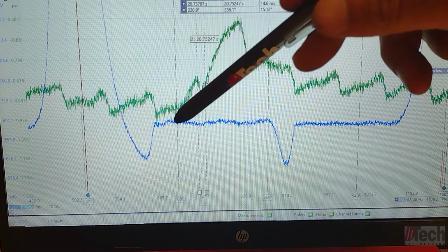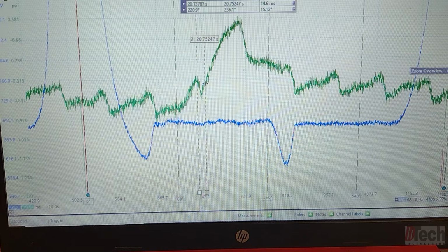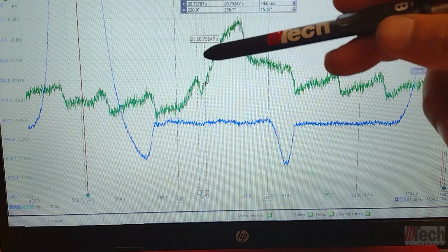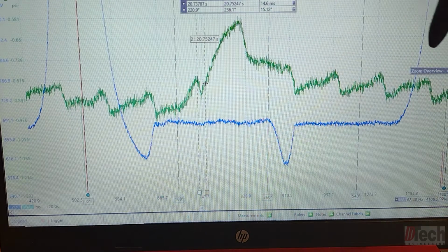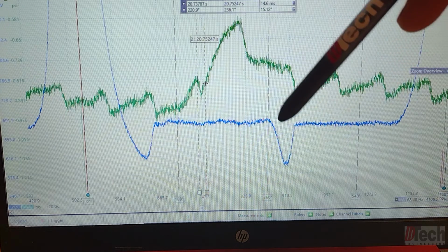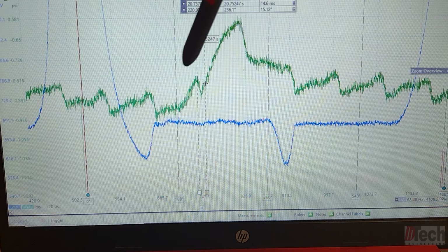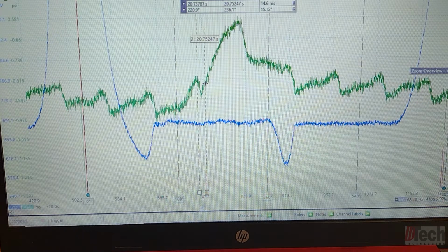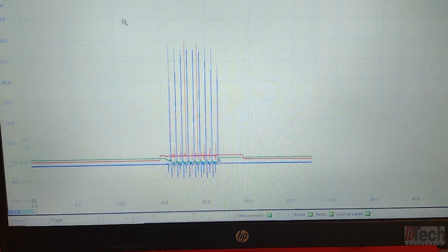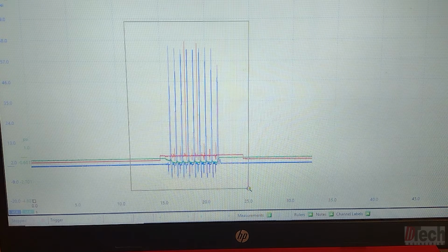most of the time from a cylinder on compression pressure, or also on exhaust. It's possible to happen on the exhaust stroke, where I've seen that actually happen on a running engine. But nonetheless, that is the relation between all the pulls compared to the pressure in the in-cylinder, and taking note of what is occurring there just before the high rise. Now this capture here is cranking in cylinder number 8.